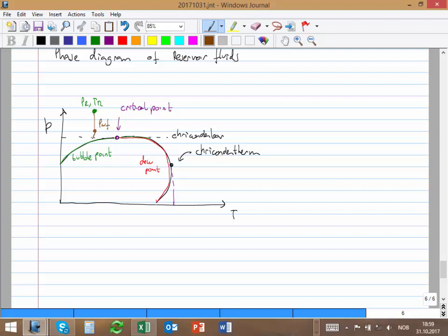But then when you start flowing into the well and through the whole production system, you are inside the envelope and you have multi-phase. For oil reservoirs you are to the left of the critical point, and for gas reservoirs, to the right. In this case, the bottom hole pressure is undersaturated, but it might be that this point could also be inside the envelope.